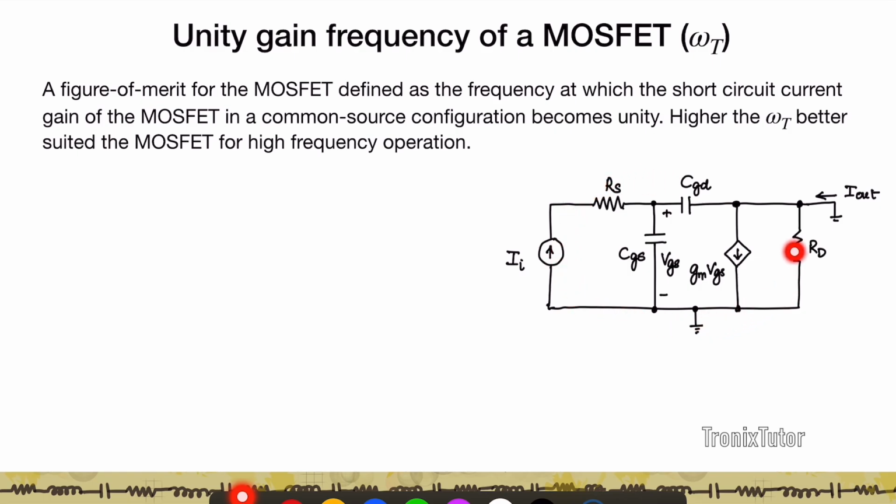So here I'm looking at the common source amplifier. So this is my common source amplifier model. I have a load RD, signal source RS. Again, I'm assuming r0 is not present, or if r0 is present, I'll lump it into RD. What I want to do is apply an input current. So remember, because we're considering capacitances, I can send in currents now. It's not like the mid-band analysis which we did prior to doing frequency analysis, where we assume the gate to be essentially an open circuit. The gate is actually capacitive. And so I have a short circuit output here, which is I out.